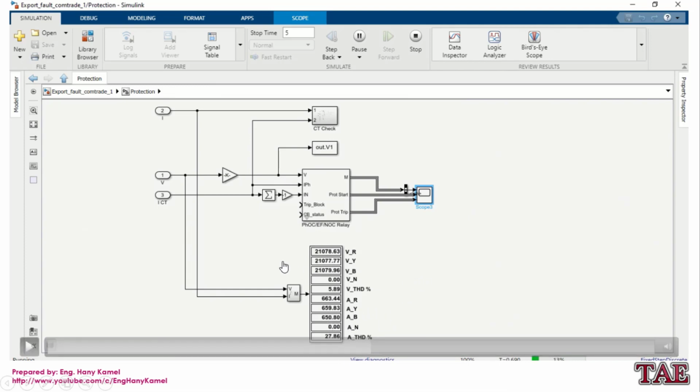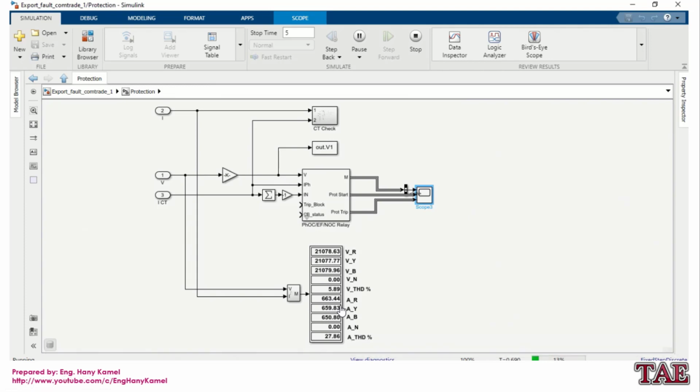Now our breaker is closed in substation 2. It will now feed the underground cable and load in substation 3. Actually, when the breaker is on, it starts to feed load directly, and also it will have some inrush current due to charging and inrush current of load and loading current.